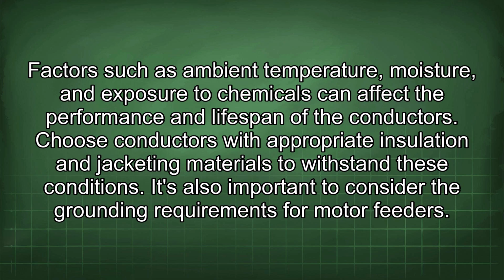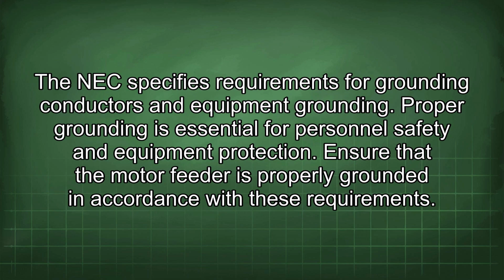It's also important to consider the grounding requirements for motor feeders. The NEC specifies requirements for grounding conductors and equipment grounding. Proper grounding is essential for personnel safety and equipment protection. Ensure that the motor feeder is properly grounded in accordance with these requirements.